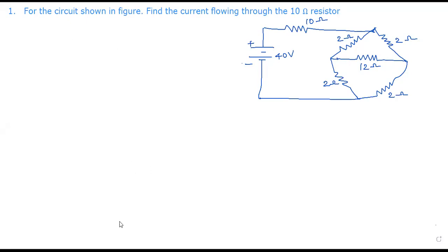Okay. So now for this video, we are going to discuss how to solve electric circuits using mesh analysis, right? Okay. So for mesh analysis, before we start solving the circuit, we should ensure that the given sources are voltage sources, right?